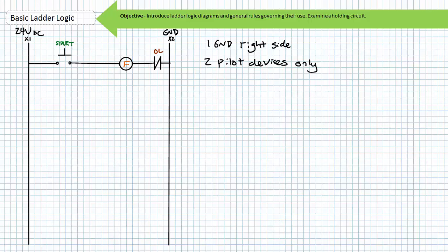Ladder logic diagrams only show pilot-rated electrically active components like switches, pilot lamps, control relays, contactor coils, and the solenoids of solenoid-operated directional control valves. Primary devices like hydraulic components or contactors aren't included. These devices would appear in the primary hydraulic or electrical schematic. Ladder logic diagrams illustrate the connection of pilot devices only.